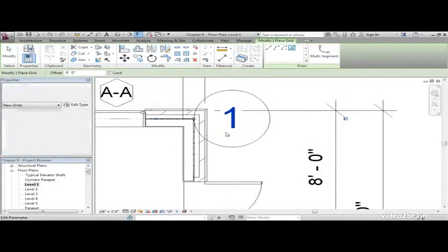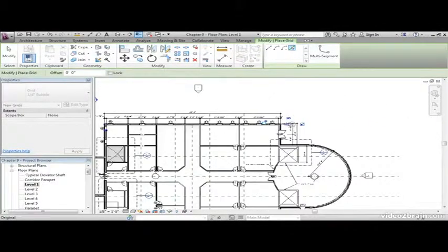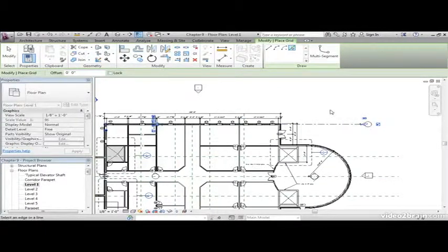Notice the bubble. We have some similar looking little icons. We have a drag icon. We can add an elbow. We can turn the bubble on or off. What I want to do for column line 1 is just come in here and grab this little grip. Pick it and slide it over to the right, just so you're clear of the radius. Very nice.